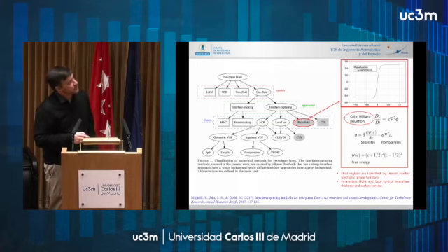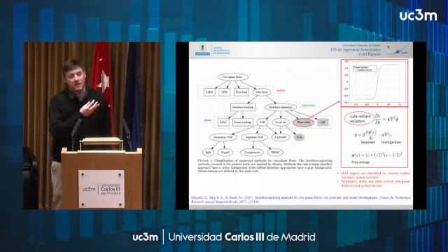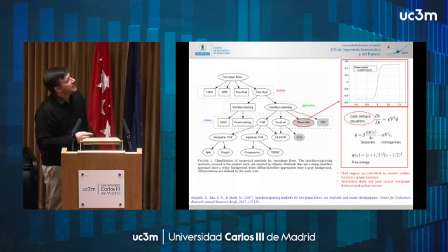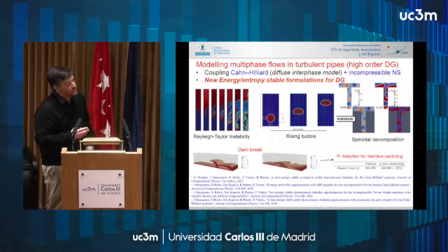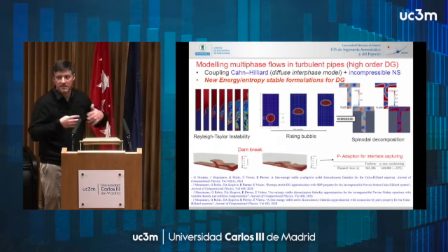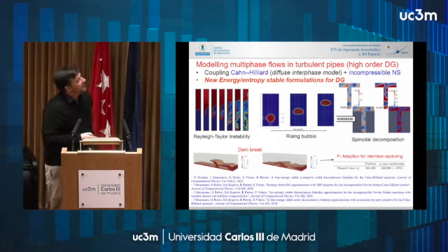So that requires solving the Navier-Stokes equation plus some additional equations, the Cahn-Hilliard equations, which are not easy to solve, I must mention, because if you plug this one into this one, you get a fourth order derivative, so it's not easy to solve, but we can do it. So we have run that for a few classic test cases, such as those ones. And what's very nice, the method is conservative, it has very nice properties, etc.